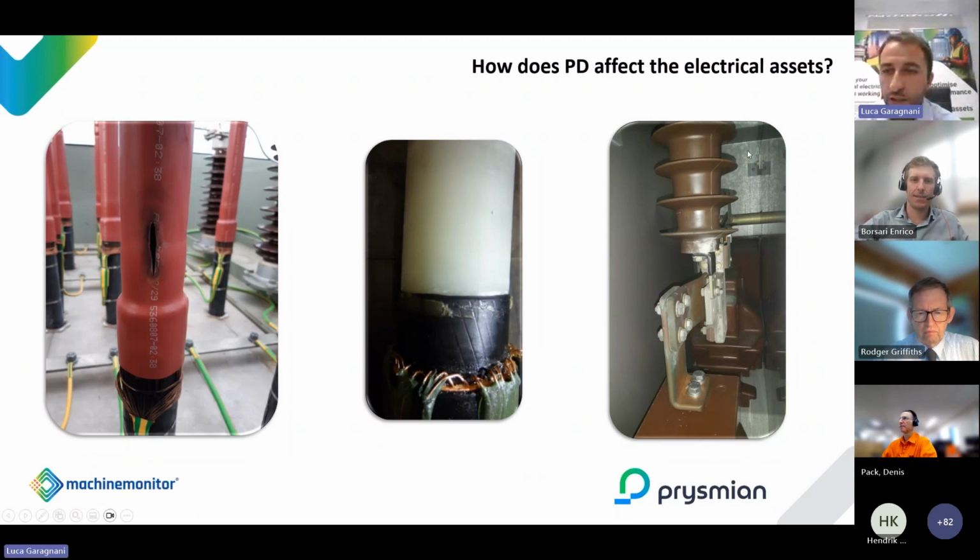And this is a picture of a gas or air insulated switchboard system, 33 kV in New Zealand. And you can see some white dust here in this location. The white dust is the evidence that they had a discharge in this cabinet. This discharge can be due to a defect on this insulation, or contamination dust, and once it triggers, it will create tracking, and it will eventually fail this system. But it also generates a lot of ozone.